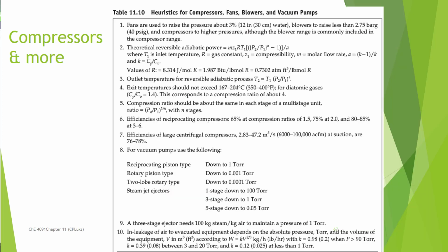And then we also have one for compressors, fans, blowers, and then also vacuum pumps is included in the same list. So fans and blowers and compressors all sort of mentally get very confused and muddled in people's minds. In some respects, they're very similar because they're used to move gases. Usually a fan is going to be used if you are really not caring too much about increasing the pressure. Okay, it'll only increase the pressure about 3%.